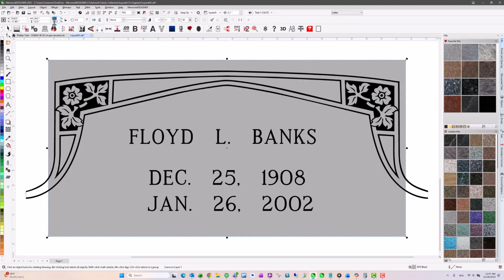If I actually want this to be 100%, I can just hit W. Oops, not there. Hit escape. I can select it and hit W, basically welding it to itself, and that resets this number to 100%. It just makes it easier in the future if I wanted to scale by a certain percentage to have it at 100%.